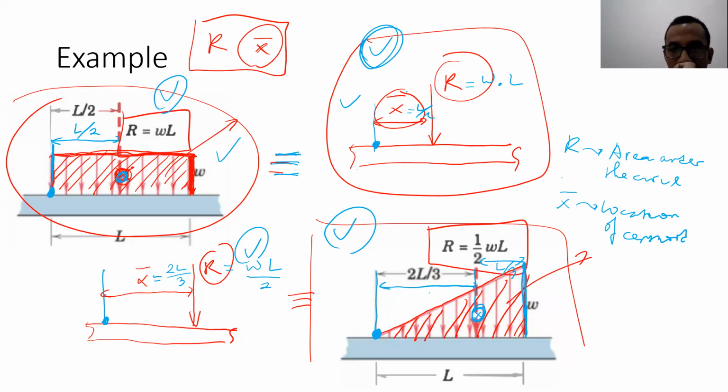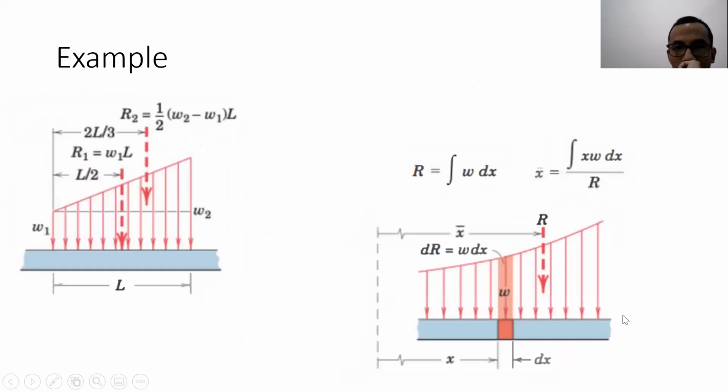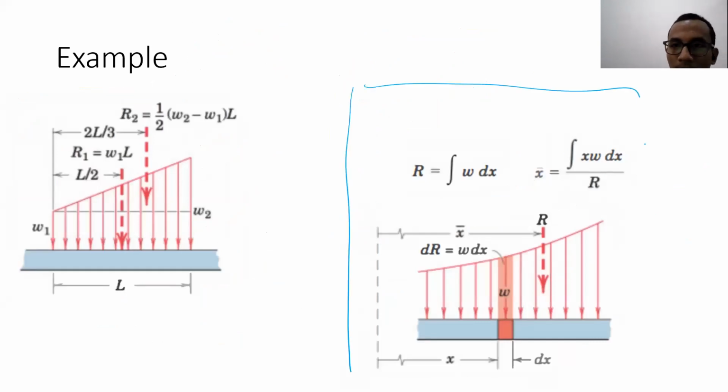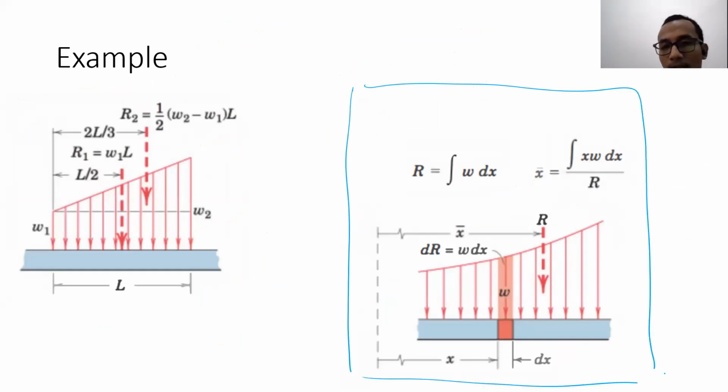Yes, we can, but using an integral. If the distributed force curve is neither triangle nor rectangle, we can use an integral, but R is supposed to be the integral of W dx.